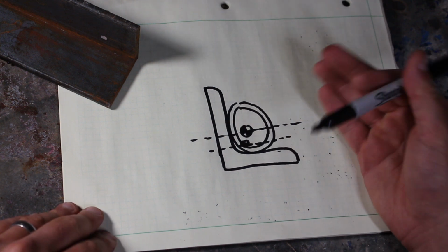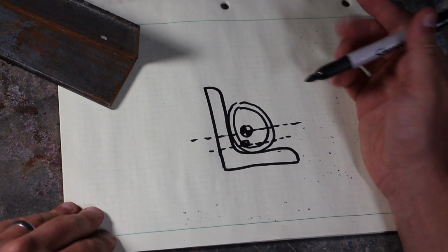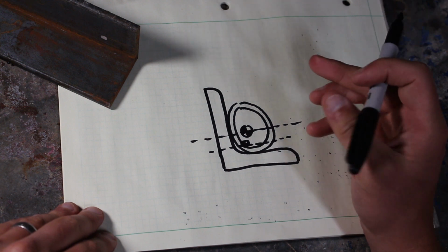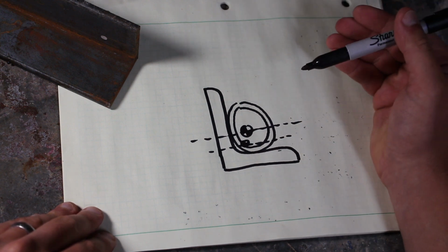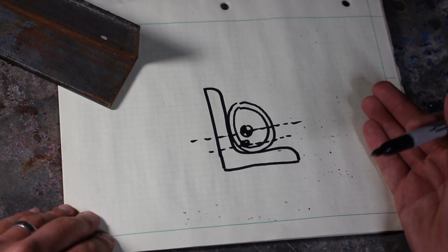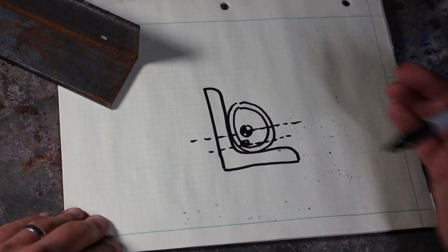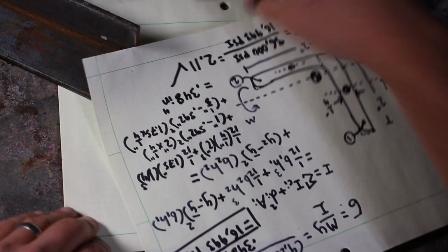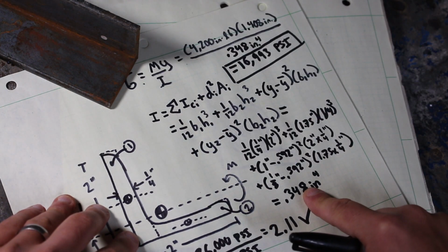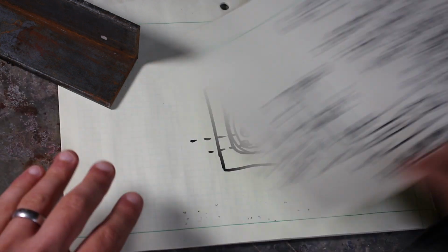When you're designing something, time is limited, and it's good to be conservative. So just analyzing the angle in this case is totally sufficient. In fact, you could take it one step further, and oftentimes when I'm designing something with angle and I just want to do a quick check to make sure it's safe enough, I don't go through all of this parallel axis theorem analysis to figure out my moment of inertia.